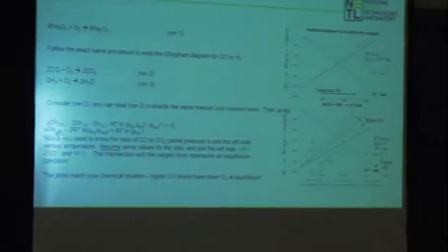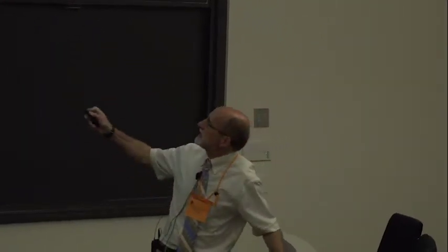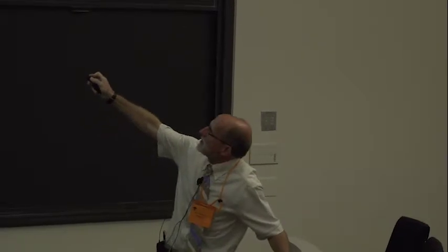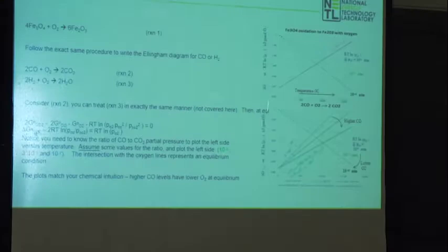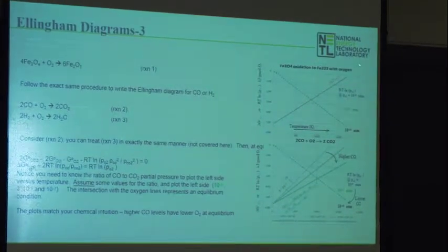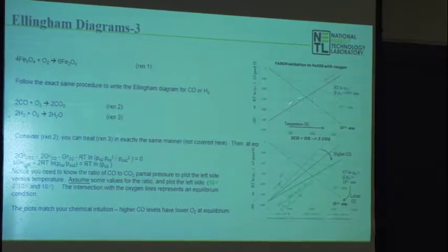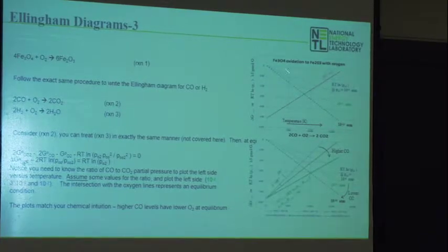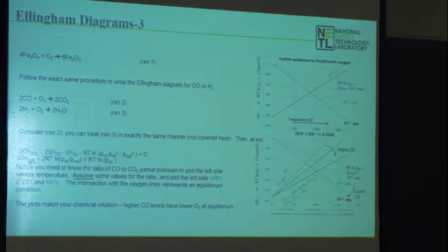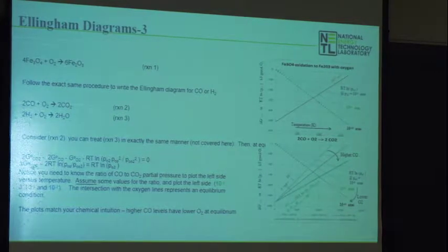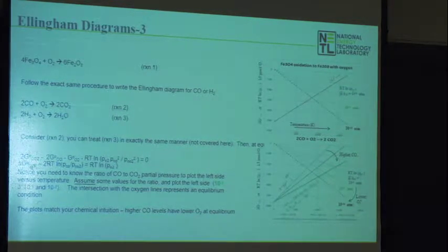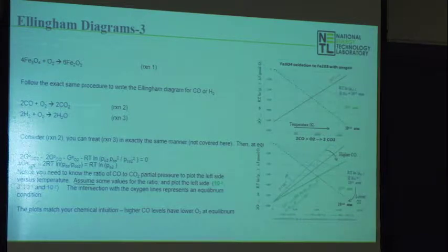For the sake of the tape, we were talking about equilibrium oxygen partial pressure with the metal and the metal oxide. We showed how to plot that up versus temperature on this scale, and then the standard change in Gibbs free energy on this scale. Here's the standard change in Gibbs free energy for that metal, the red line right here. Here are the different values of oxygen partial pressure. At any given temperature, I can now predict what partial pressure of oxygen there must be to establish equilibrium.